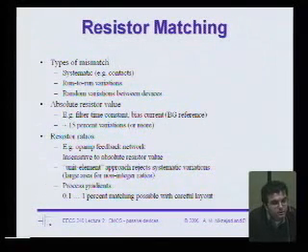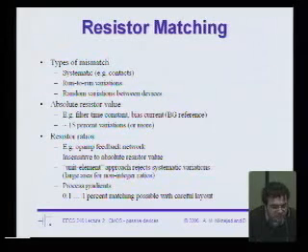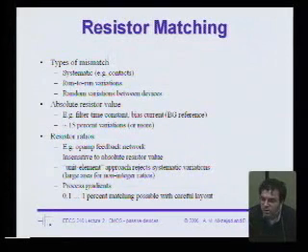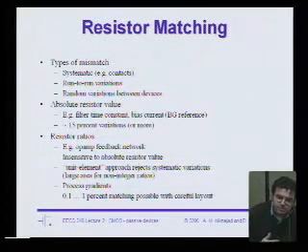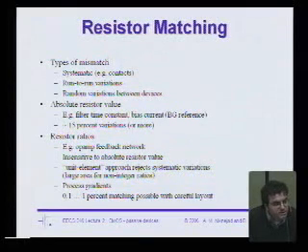There's two places where we just don't have a choice. One of them is a band gap. So if you build a band gap, you get a really nice voltage, which is more or less independent of all the resistor values you use to build that band gap. But to turn that into a current, you need a resistor. And if that resistor is on chip, your currents are all going to vary on chip with that resistance in an absolute fashion. So that's one place where we kind of have to bite the bullet. A lot of times people will use an external resistor. Those have one precision external resistor, let's say a 0.1% accuracy resistor, but that's okay because it sets up the bias for the entire chip. So I can live with one external resistor. The other place is time constants. Because time constants are like RC time constants, then as C varies and as R varies, the time constant will vary as their product. And so it's not untypical to see variations on the order of 15% or more.